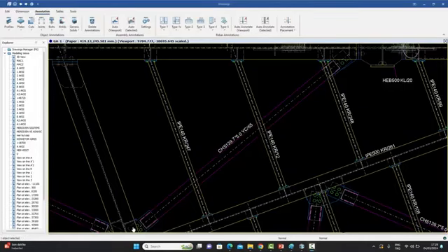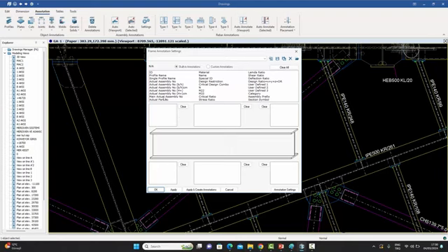Now, the next question obviously is that now that we have created these custom annotations, how do we actually use them? So you do know how to use the old annotations, which are the built-in annotations or off-the-shelf annotations. They're over here, if you remember. And you go to the annotation settings where you select the built-in annotations. You basically press the same button again. This is what it used to look like. This is what it still looks like. But now we have at the top built-in annotations, which is what we had before, and we also have custom annotations. This is with regards to profiles. Obviously, there's the same thing with plates and with bolts and with solids, etc., and with rebars.